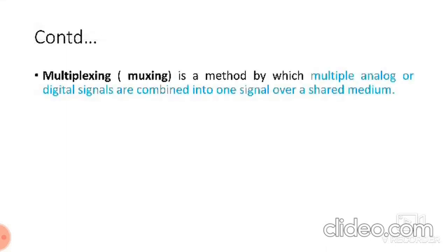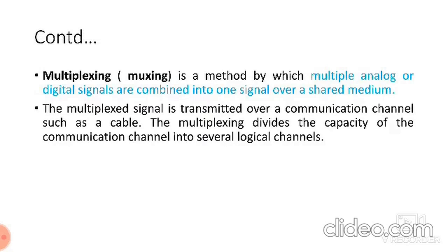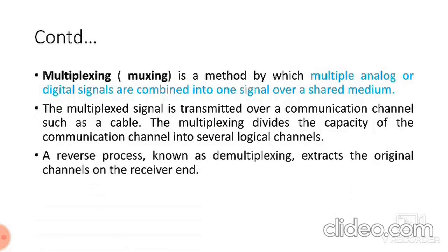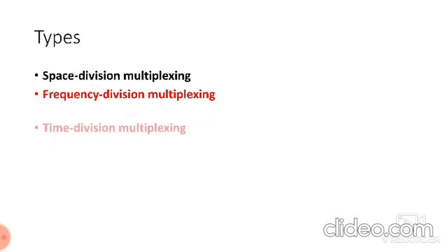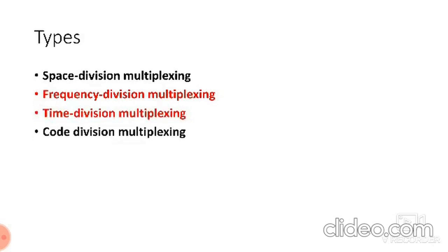Multiplexing is otherwise called MUX. That is the method by which multiple analog signals are combined into one single channel. Here it uses a low pass filter. Each channel to be transmitted is passed through a low pass filter. The outputs of the low pass filters are connected to a rotating sampling switch, and this switch rotates, and each time selects the channel which is to be shared. So simply, this is multiplexing, TDM.